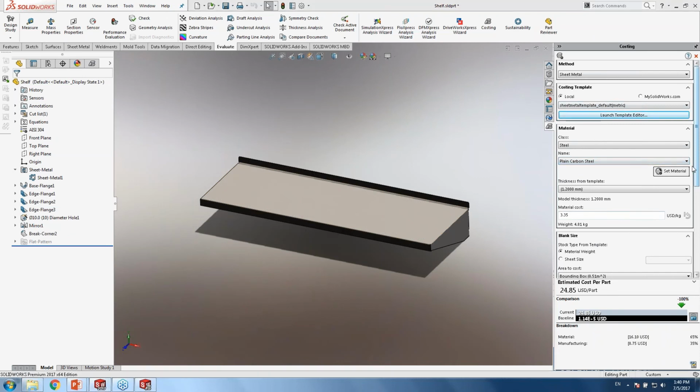And remember, at any time when you make a major change in your templates, remember to close and then get back to the costing. However, we can just get and hit that. So our costing now is 2,614 AGP. Ask yourself, does that make sense? Is it really a good number? Which means that I did not make any mistake in typing some numbers. For example, you may type millimeter instead of meter, and in this case you will find this is a very, very large number.